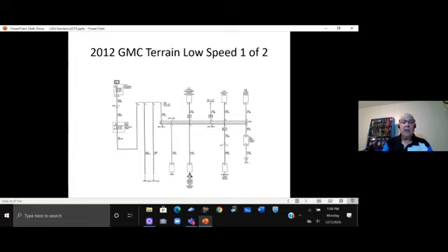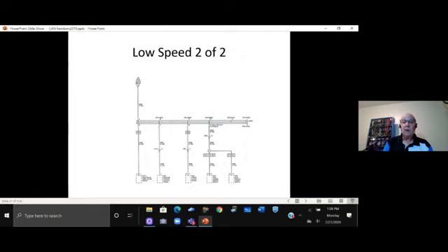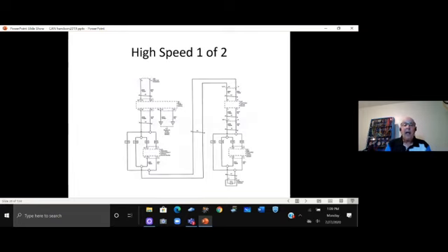So here's our low speed. Again, if you look at the DLC, which is mid to left on the screen, you got pin 16, you got 5, you got 4, you got pin 1. Okay? There's another low speed, or another series of 5 modules which are on the same low speed connected together. Okay? Then we have one high speed. Now this high speed, and go to the DLC, upper left. What pins? Pin 6 and 14. So this is going to be the first high speed that you'll find on cars. They're going to be pin 6 and pin 14. Okay?